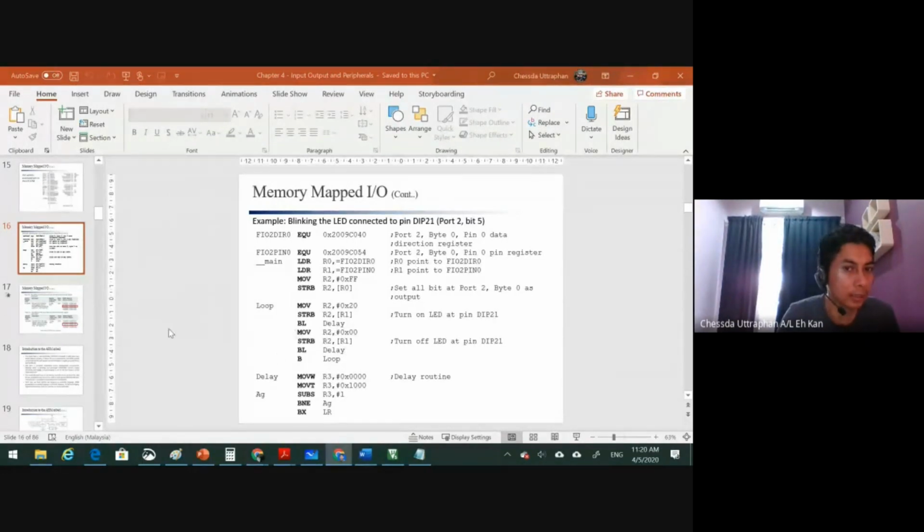Okay. So this is the program to turn on, right? Hexadecimal 20. Why 20? Because 20 is 0 0 1 0, and the 1 is in bit 5, all right, to turn the LED on, and then send 0 to the output. We have the LED off. Okay. All right. Now, any question? All right. So that is the concept. You see, wanting to turn on the LED is not that easy.